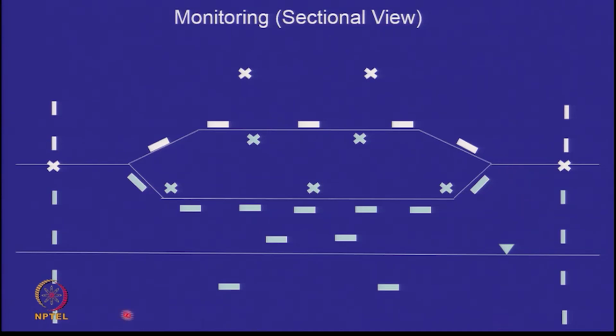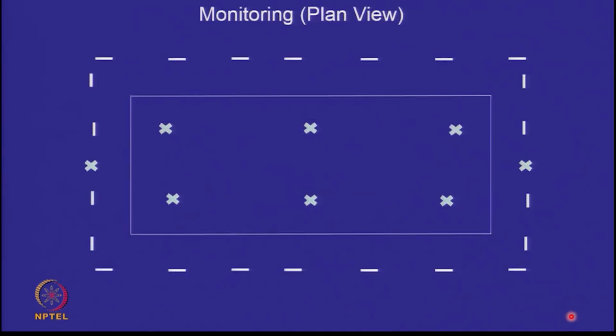We are basically focusing on how to monitor the environment beneath the landfill, that is to detect early and to ensure that no contamination crosses the boundary of the landfill. In plan also, we would be doing monitoring around the perimeter of the landfill and at various points above the landfill, on the landfill surface and beneath the landfill.